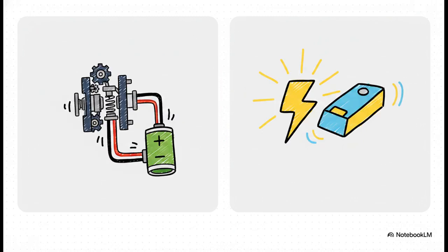Next, we separate them by their power requirements. We've got active sensors, sometimes called parametric sensors. Now these need an external power source, some external juice to actually operate. Think of strain gauges or carbon microphones. On the flip side, we have passive sensors. And these are self-generating wonders. They literally create their own electric signal from the stimulus itself, no external battery required. Thermocouples and photodiodes fall right into this highly efficient category.